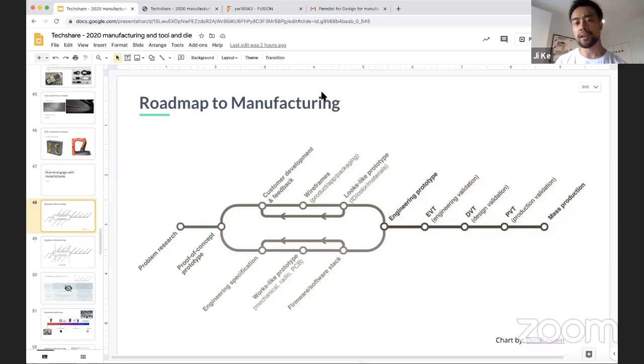So personally, I like sheet metal because if you use it creatively from the design process on, you can make very beautiful, very well-made products for very cheap, right? Sheet metal cost is significantly lower than the CNC cost when you're working with metal. So if you use it right, I do prefer sheet metal, but sheet metal, of course, has a lot of limitations to the ultimate geometry, right? It's planar kinds of components, but this is something I do like when it's used right and when the product allows.